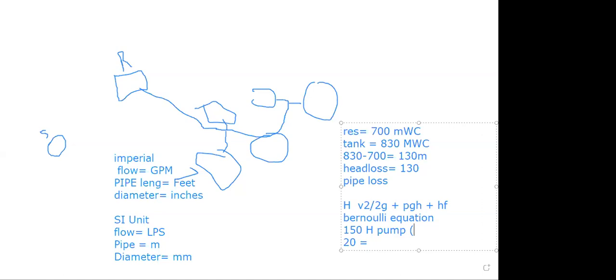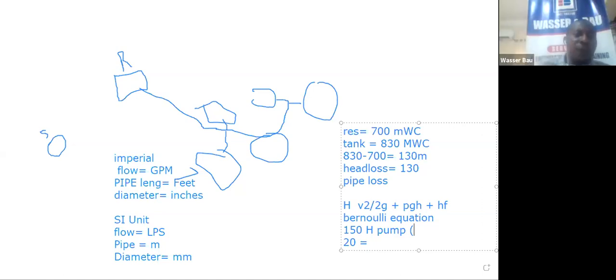Now, if you run it and it is not delivering water, Epanet will tell you. That's a good thing. That's why some people say Epanet helps you to dimension your pump. Actually, Epanet helps you to check your pump. And if you agree with me, checking something and dimensioning is just similar. If you throw something at it and it doesn't like it, it will tell you no, so what you do, you iterate.